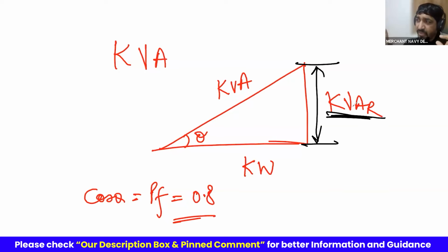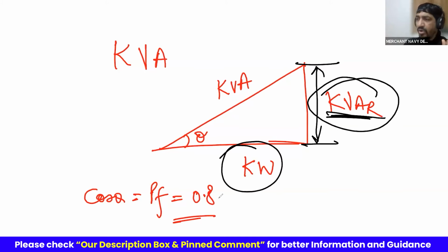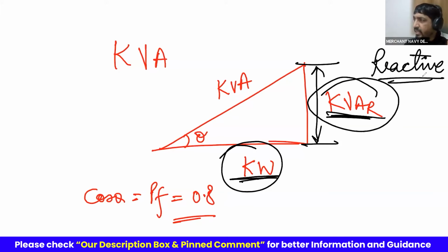If the voltage was not the same, the generator with a higher voltage will end up taking more reactive load, even though their kilowatt load may be the same. This is the concept here. Kilowatt load may be the same because RPM is the same, or before paralleling the frequency was the same, right? The reactive load will be shared equally only if the voltage before paralleling was the same.